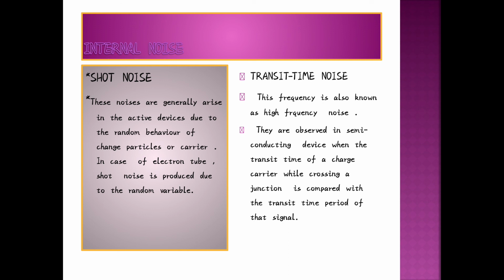Next one, transit time noise. Transit time noise, at high frequency, is also known as high frequency noise. It is observed in semiconducting devices when the transit time of the charge carrier while crossing a junction is comparable with the time period of the signal.